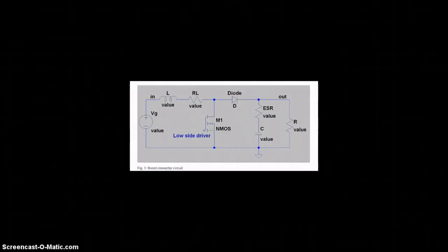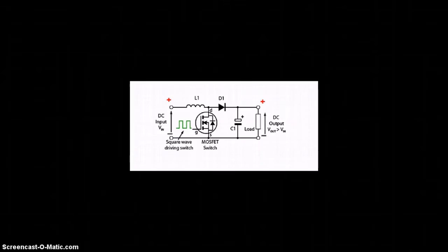This is the circuit diagram that we are going to simulate and also explain. It is a bit different from other boost converters as we have included parasitic resistance in the passive components, and there is an on-state resistance in the active component. For understanding the explanation and working of this boost converter, we are going to refer to this circuit. In this circuit, the DC input is shown.